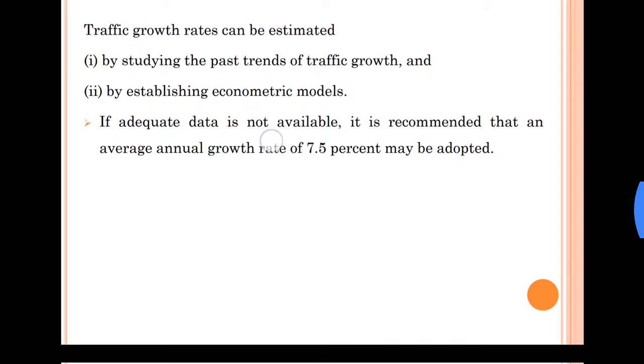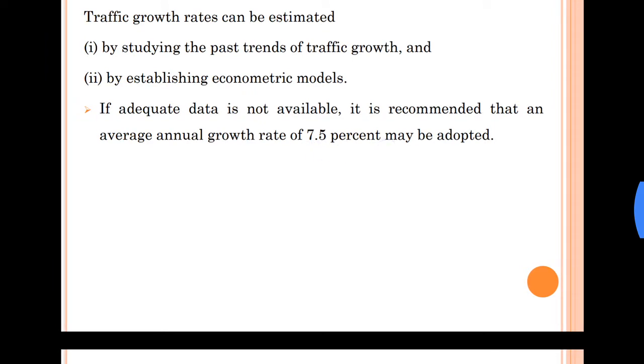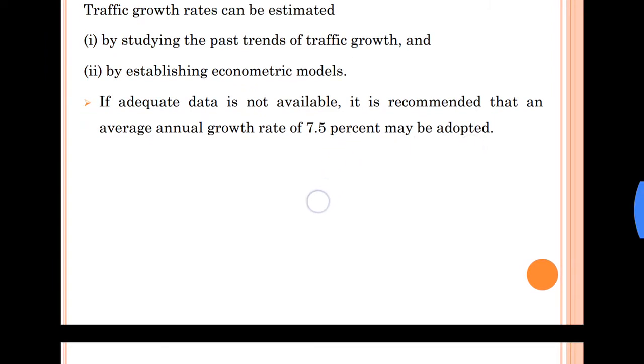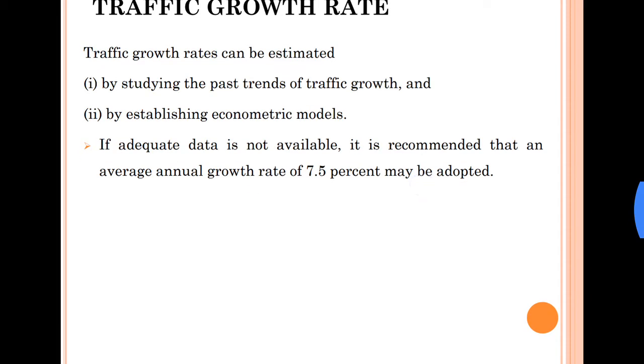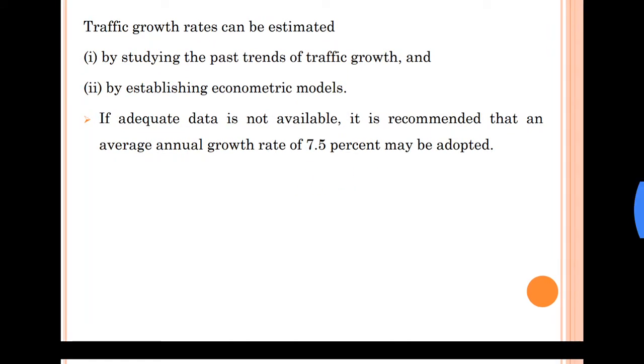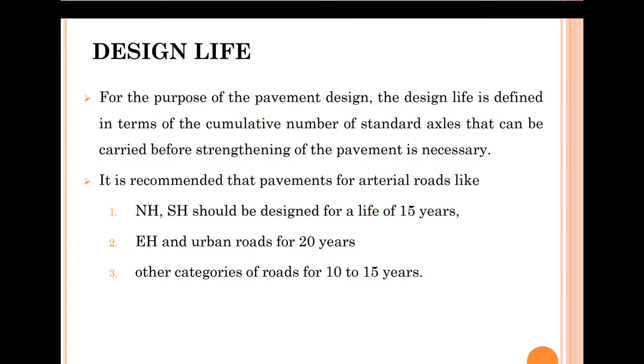If adequate data is not available, it is recommended that an average annual growth rate of 7.5% may be adopted. If we cannot obtain the growth rate, then we have a standard value that is given by IRC, that is 7.5%. Then we have design life.